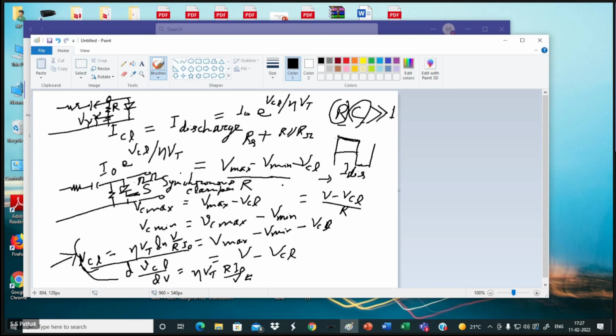Clamping, I know, if it is clamped here, it should come like that. So the 0 has gone, 0 has come over here. It becomes flat. So R and C both should be very large. Source resistance may be small. Your forward Rf might be small. Rr can be large, fine. But R and C should be large. That is the practical clamper circuit.